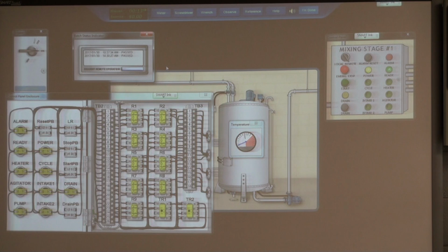What is the coil pin numbers of the relays? 2 and 7. All right, what is the common for the left-hand side of that relay? Pin 1. What's the normally closed of the left-hand side? 4. What's the normally open? 3. What's the common on the right-hand side? 8. What's the normally closed? 5, and normally open? 6. There you go. Just like before. Exactly like before. And that's pretty much industry standard. That's not to say there are not relays out there that don't follow that, but I'm just saying that is pretty much an industry standard.